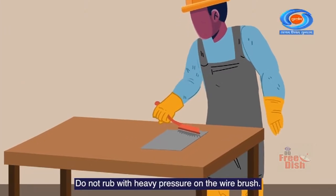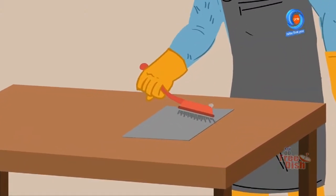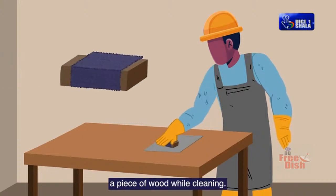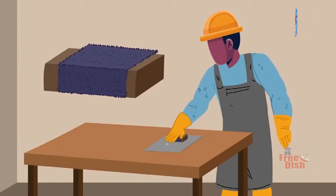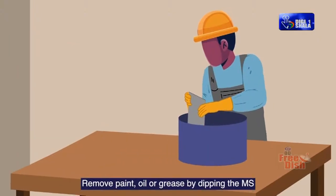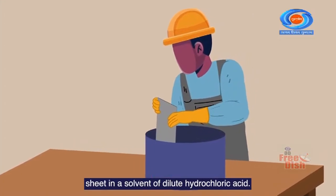Do not rub with heavy pressure on the wire brush. Use the emery paper rolled on a piece of wood while cleaning. Remove paint, oil or grease by dipping the MS sheet in a solvent of dilute hydrochloric acid.